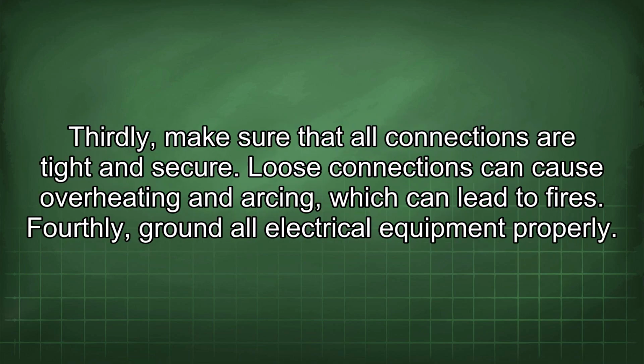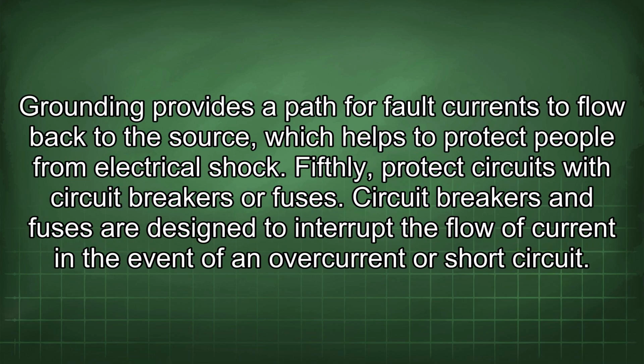Thirdly, make sure that all connections are tight and secure. Loose connections can cause overheating and arcing, which can lead to fires. Fourthly, ground all electrical equipment properly. Grounding provides a path for fault currents to flow back to the source, which helps to protect people from electrical shock. Fifthly, protect circuits with circuit breakers or fuses.